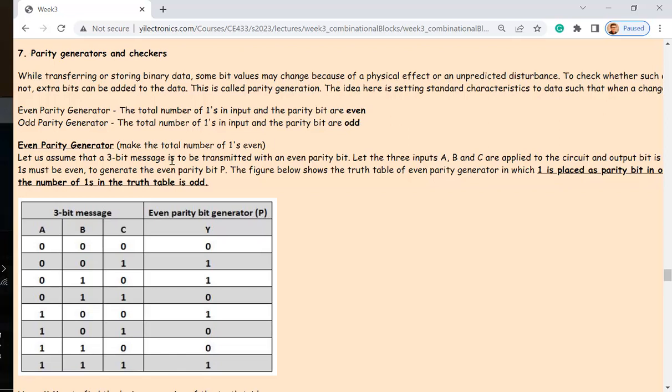You want to make sure of the data, because sometimes there will be some electromagnetic interference and noise that will probably flip some of the bits, right? So it's going to get errors. So before I send it, I set up the 2 systems so they have an agreement that I'm going to use even parity. Which means I have 100 bits to be sent, and this receiver has 100 bits to be received, right? So we already programmed both sides, and the engineers know that there will be an even number of ones in the 100 bits.